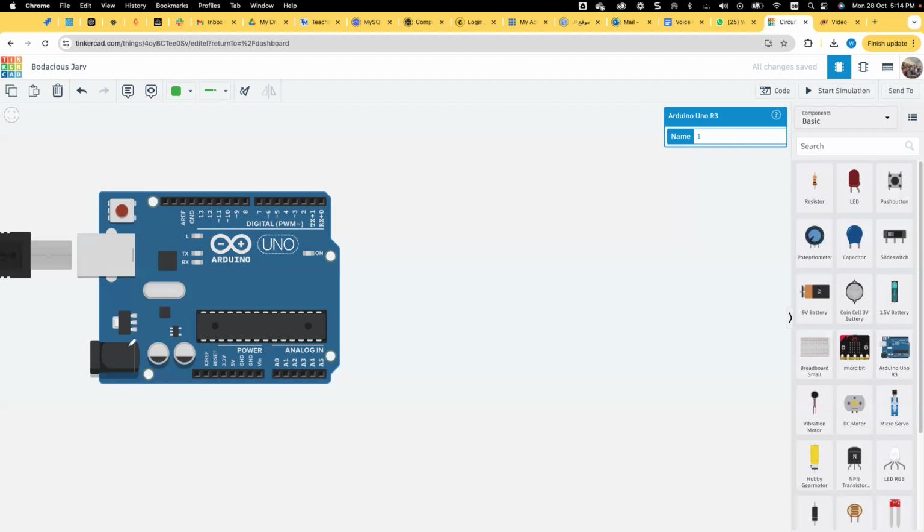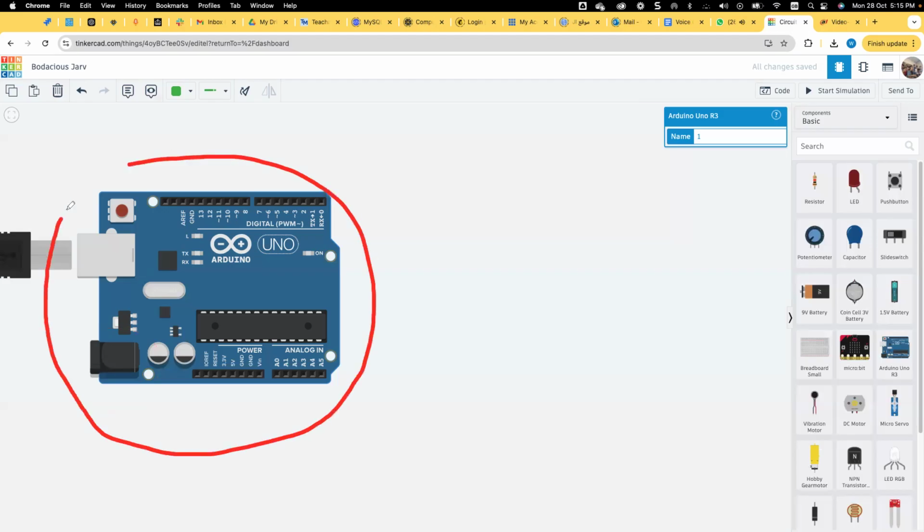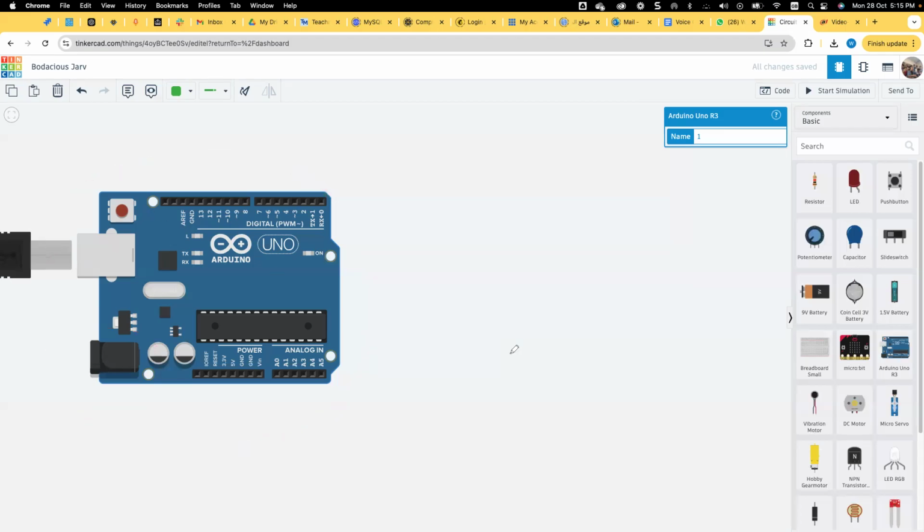And the second input is for the 9 volt connector, if you want to keep the power on the board without connecting the Arduino board to the computer. Here, keep in mind that on the Arduino board, I can't upload more than one program.